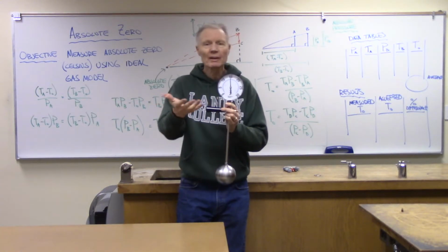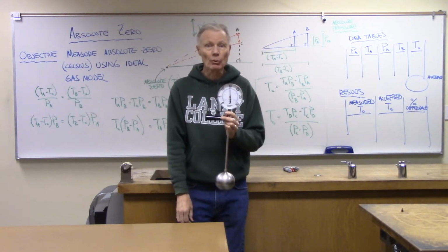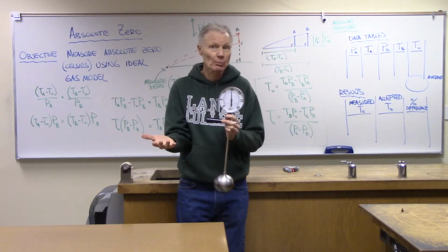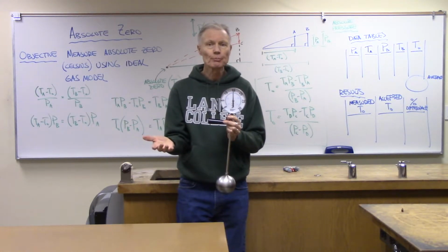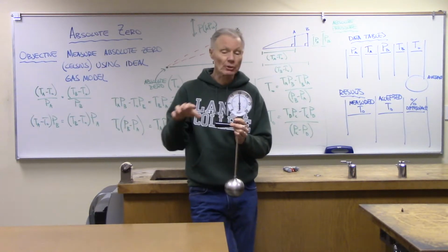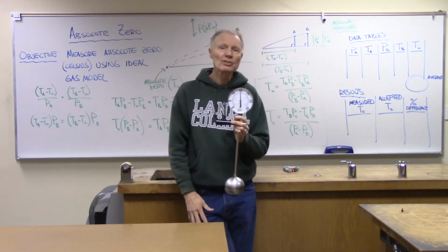You know, you're used to picking up maybe a typical pressure gauge that would read zero, right? You pick up a pressure gauge and you look at it and you go, well, it reads zero. Is there zero pressure? What most gauges are designed to do is measure pressure compared with atmospheric pressure, compared with the surrounding pressure. But these devices are designed to measure the absolute pressure.